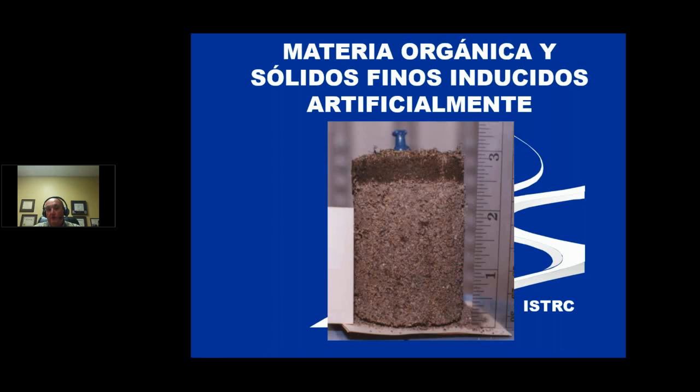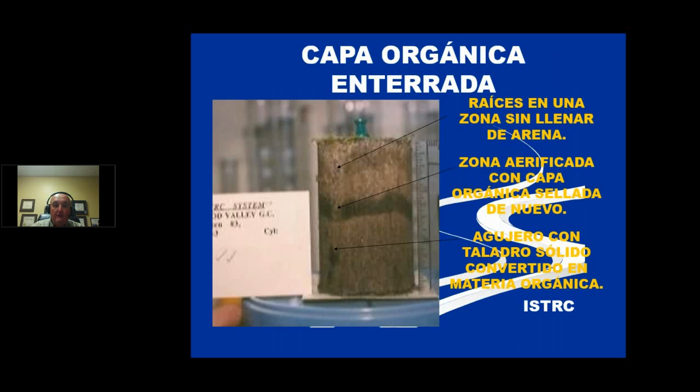And then you may also have some chemistry involved here, where what we've learned is that sodium itself wants to deflocculate our organic matter and our clay. What does that mean? It means it wants to pull it apart into smaller components. Once the organic matter and the clays are pulled apart into their smaller individual components, they flow with the water and can start contaminating the air pores. This green happens to be fairly young, and it hasn't started migrating yet. But we do want to start monitoring the chemistry as well.